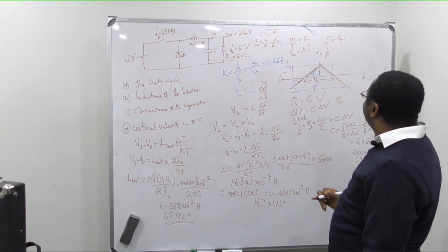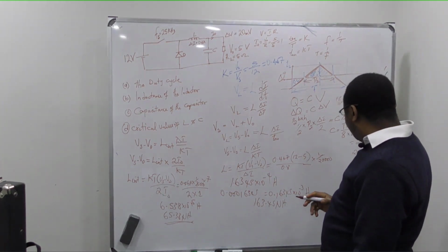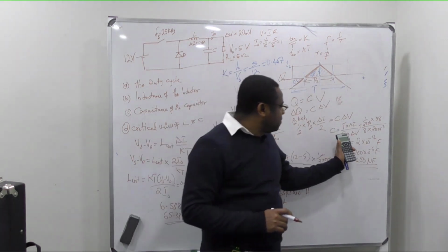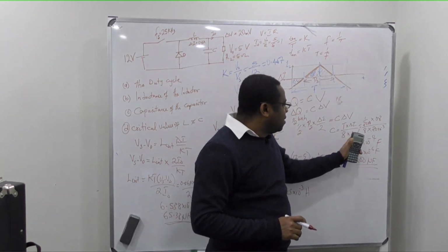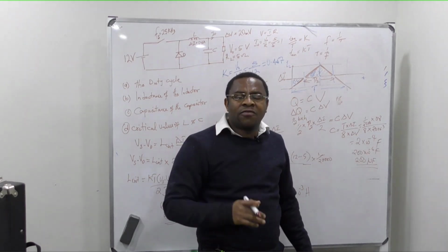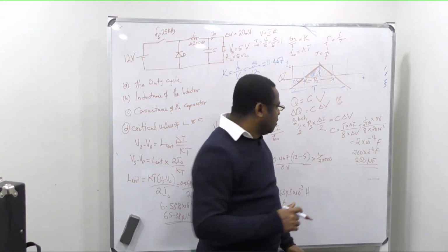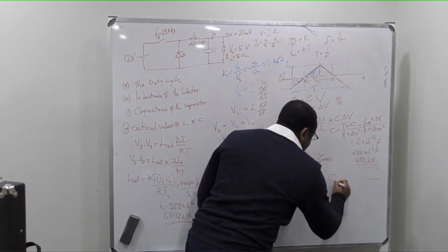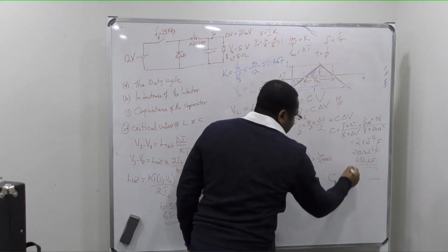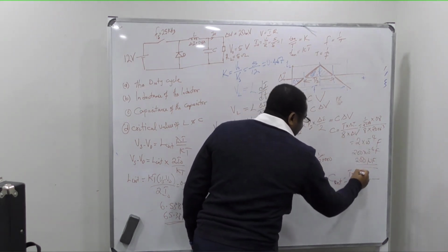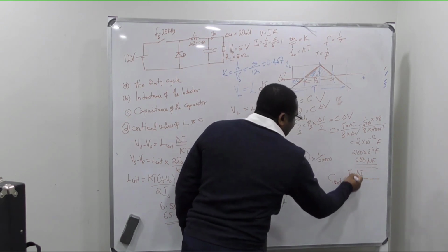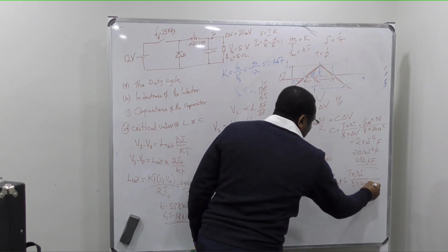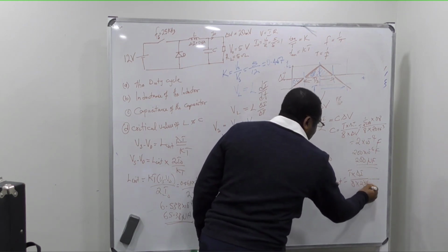All right. What do you do? Remember, here I said critical value of the capacitor, C critical, delta V will be twice the output voltage. So here we write the capacitor critical value is T times delta I divided by 8, times twice VO, 2VO.